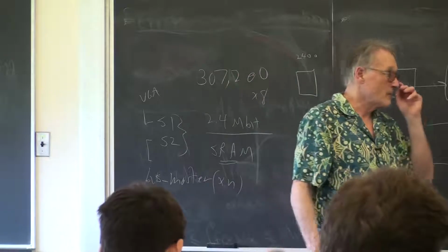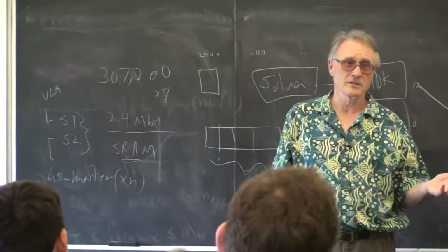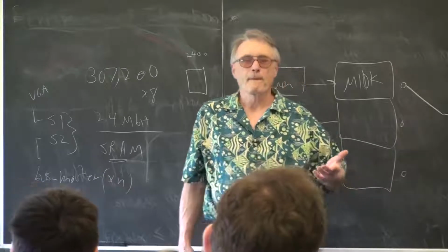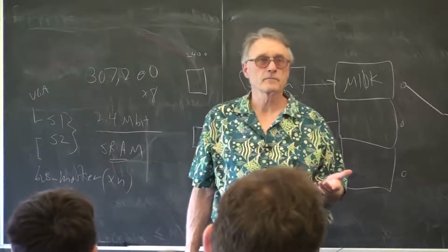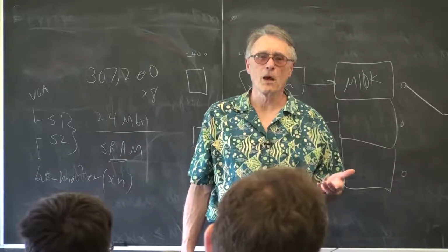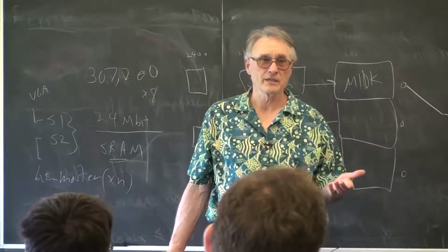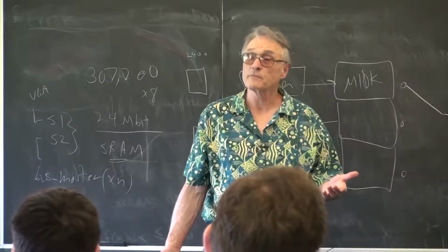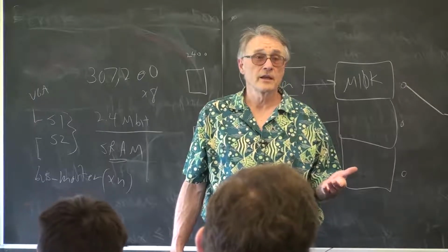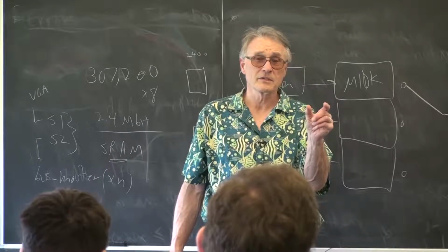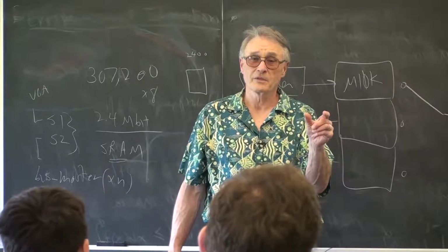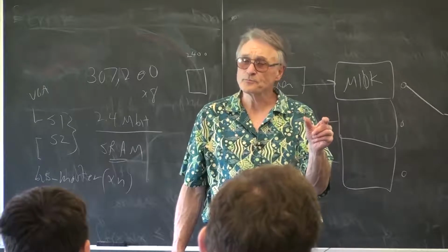The FM transmitter, you can't get 100 megahertz direct digital synthesis out of these machines. So what I did was to synthesize 4 megahertz and to use the 15th harmonic. It's a square wave, so it has a strong 15th harmonic. It's 1/15 the strength of the fundamental. Use it and modulate the frequency by 0.1%, and you can play the result through a standard FM radio.